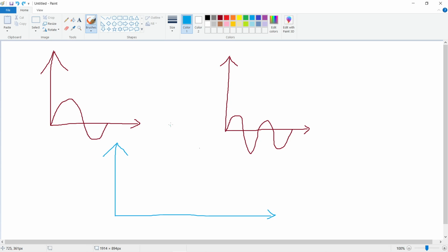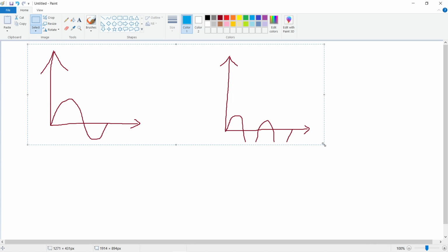And whenever it is bandwidth, let's say the lowest component you have is 100 hertz. Taking this example, both the sine waves, this is 100 hertz, and this is 200 hertz. We can't take this into consideration because this is not a composite signal. Both signals are individual, so this representation that we did is wrong. So again, in both cases the bandwidth will be the same, that is 0.